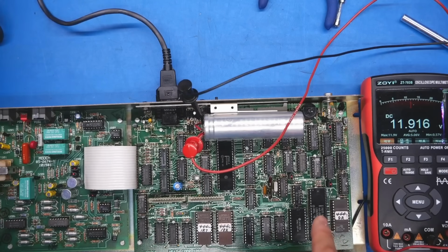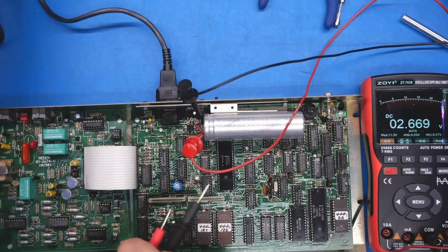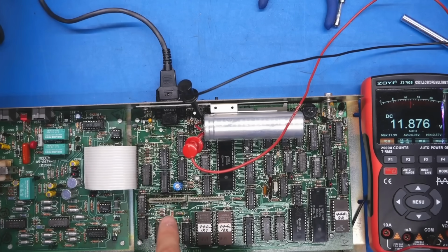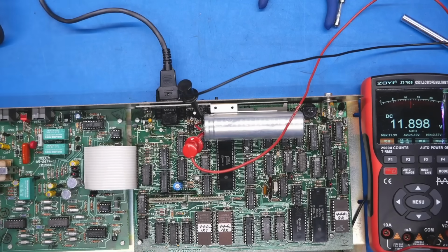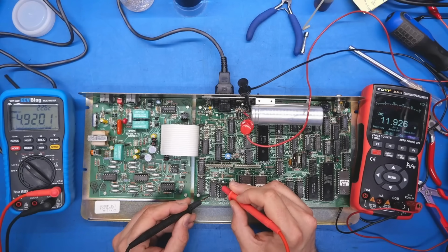I'm glad the power supply works. Let's pull it out of the wall. Okay. So that's interesting. I don't know why we're not getting clicks here. I need to measure the voltage coming out of the regulators. Yeah, plugged into the wall. We're getting the DC volts on the cap, and we are getting voltage.